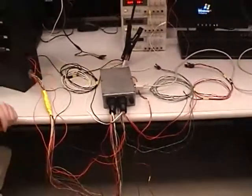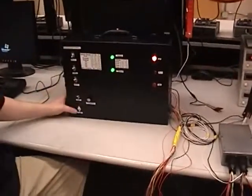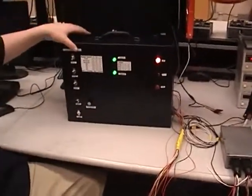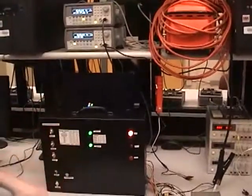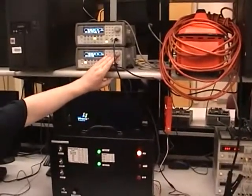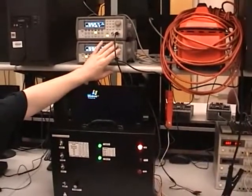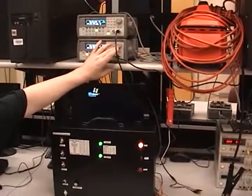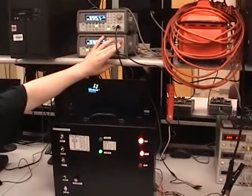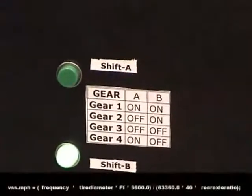And we'll start walking you through the states now that y'all have an understanding of what to expect and what we hope happens. Right now you can see that we're currently in gear 1 by both lights being off. If I jump here on the signal generator and we start increasing the speed, you can see that it went from first gear to second gear at 370 hertz.